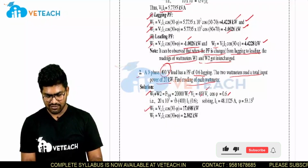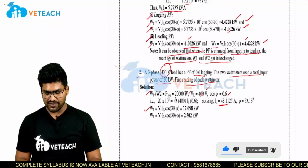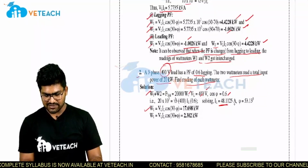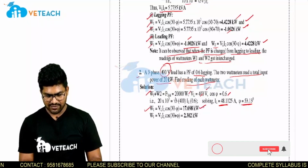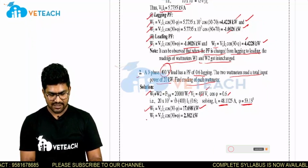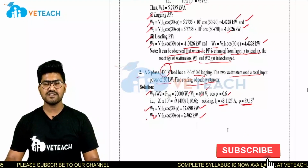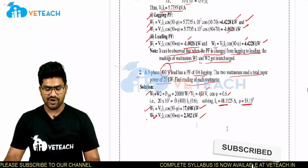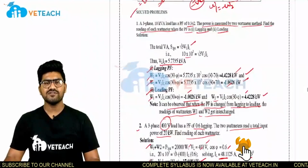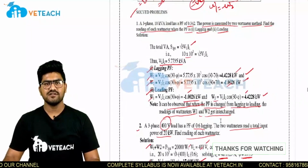So VL is 400 volt, IL is nothing but 48.1125, and phi is 53.13 degree, so cos(30 minus 53.13). So I am getting 17.698 kilowatt. Similarly, W2 I am getting as 2.302 kilowatt. So this is how we calculate the power by using the 2 wattmeter method of balanced or unbalanced circuits. Thank you.